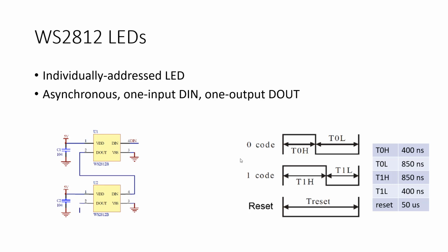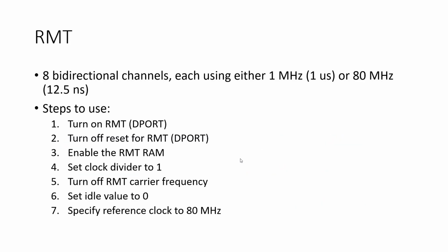And now the problem is to call them addressable is not technically true because there's no way for me to change the color of the third LED on the chain alone. It's impossible. Can't be done. If you want to change the third one, you've got to change the first, second, and then the third one, right? So it's a little bit of a misnomer. They're not exactly addressable.